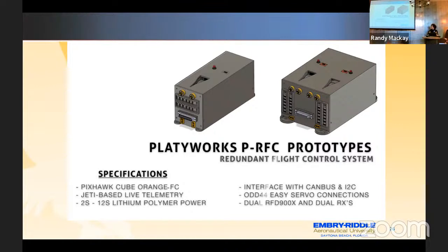And as you can see, beginning the VTOL process, but there's still a lot of work to do. There are many different states you have to account for, such as transition between vertical lift and horizontal. What does it do in horizontal flight? What does it do in a standard flight and vertical lift? And that's just, the Lua script just blows up in size as a result.